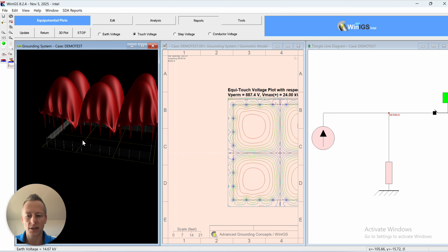And that was another thing to talk about, the ground rods. Where do you put ground rods and how do they help? When you put the horizontal conductors in, they're all 2.5 feet below the surface, and they help to equipotentialize all the dirt. Ground rods reach deeper down into the earth and effectively disperse current lower down deep into it where it doesn't have to go through as much earth.